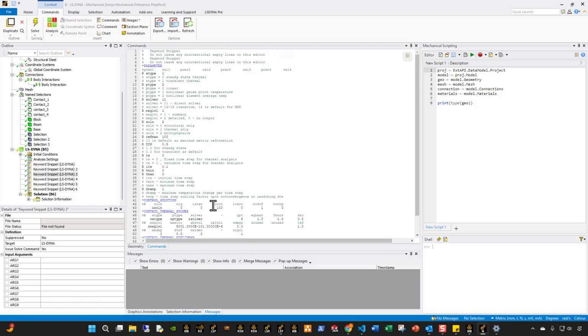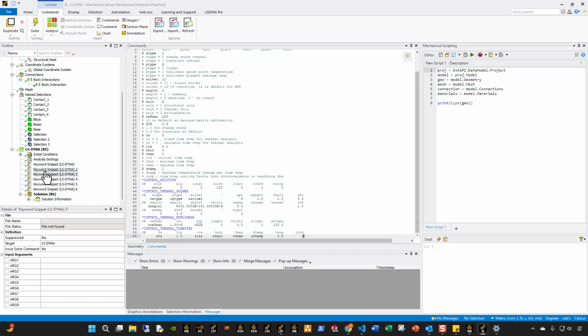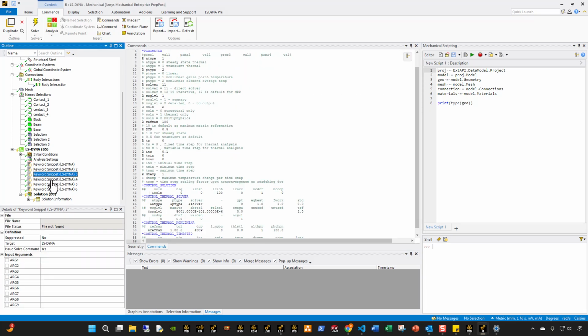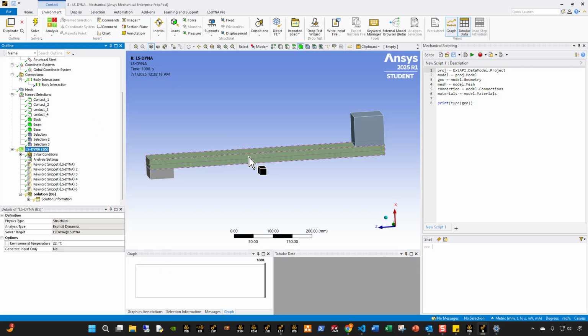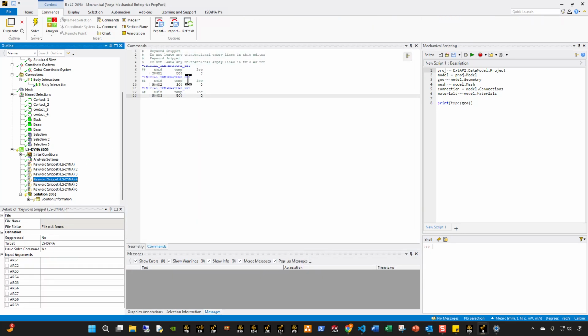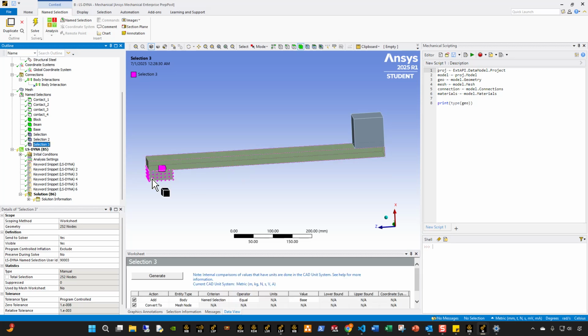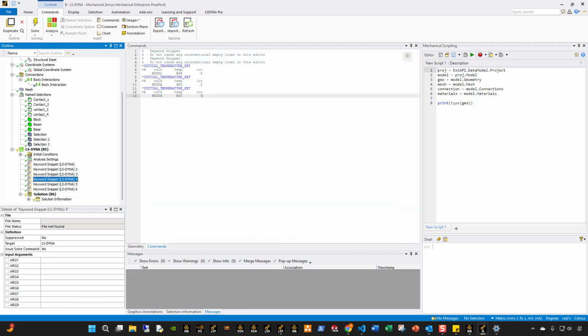Next one, we're gonna do our thermal control card. This is what defines the thermal solver behavior. This is what defines the structure solver behavior. Okay. Initial temperature. Now the initial temperature is important because each of these bodies needs to be assigned an initial temperature so that you have a thermal flux going from high to low, right? That thermal flux is needed for the initial temperature setting. So this 9001, 9002, 9003 are the initial temperature for these three bodies, which defines the thermal flux directions that we wanted to do, right?